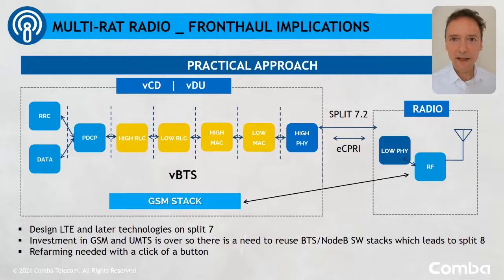How do you practically address this? Let's look at GSM. Operators have stopped investing in GSM for some time now. Yet, GSM is embedded in our society and supplies critical services. For this reason, existing GSM stacks will need to be reused as much as possible to avoid having a reinvestment in something that is already working. For the radio, this means two different logical interfaces to the same radio, both the new OpenRAN 7-2 interface, but also a split 8 interface, where the traditional IQ samples gets into the virtual BTS for the future.